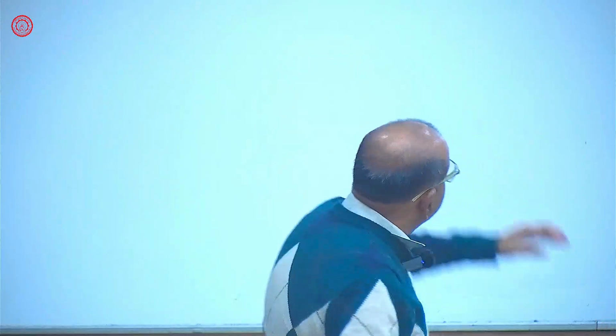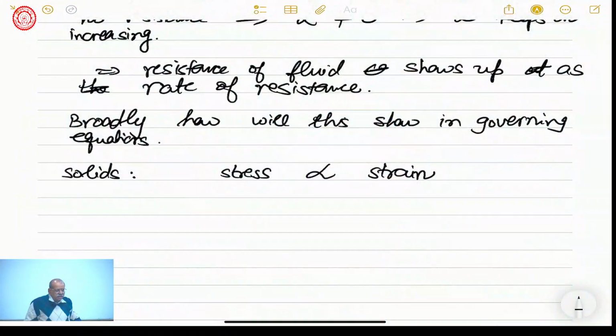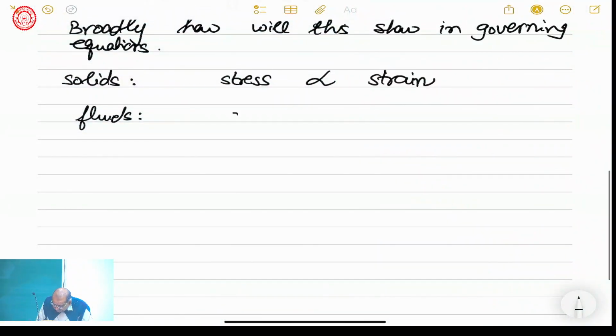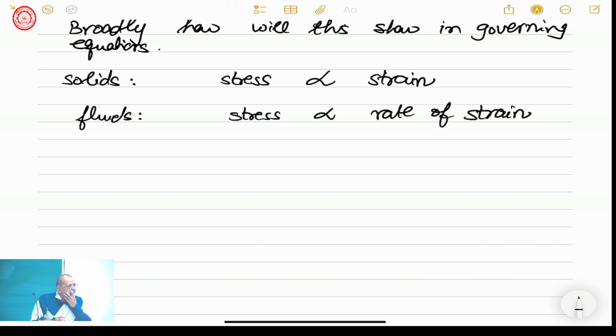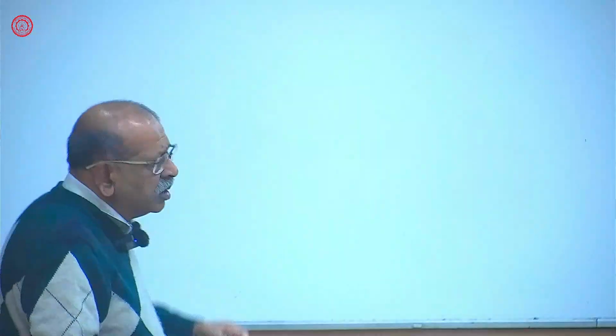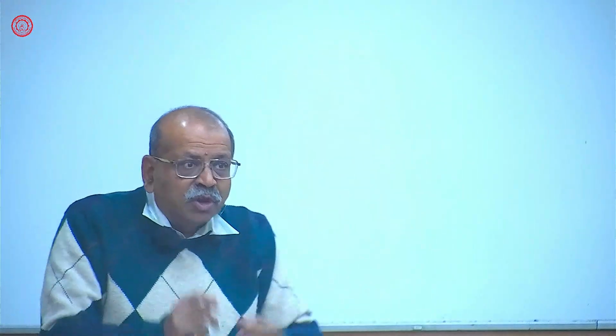Okay? So now, what would we expect in fluids? What would stress be proportional to? Rate of strain. Instead of strain, what we will expect in fluids is that stress will be proportional to the rate of strain. And this is the big difference in the constitutive nature of solids and fluids.